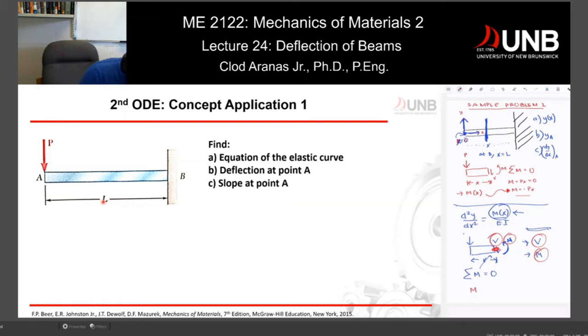And we have a force P at the end, like this one, and we have a distance X right here. So at this point, we have P times X counterclockwise. So it's plus Px is equal to 0. And then I can say that the moment at the end of my beam, M, is equal to negative Px. So this would be my M as a function of X.